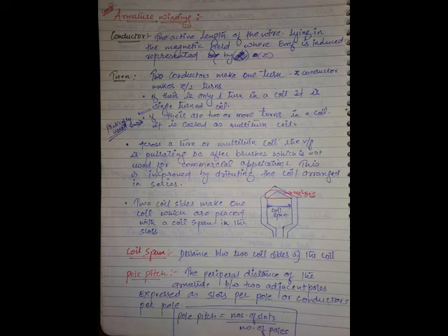You need this formula particularly while calculating demagnetizing ampere turns per pole and cross magnetizing ampere turns per pole in the armature reaction topic. I'll make you understand clearly regarding that. In electrical machines, we are interested in electrical degrees but not mechanical degrees. Remember this simply.